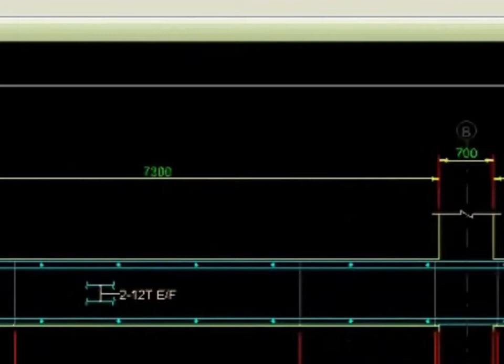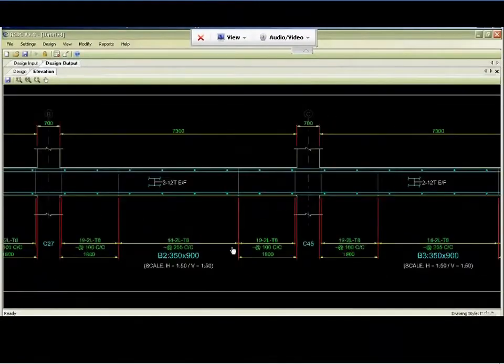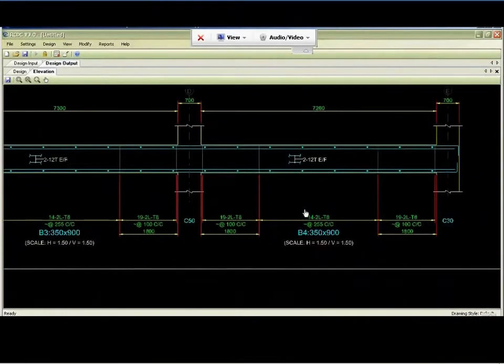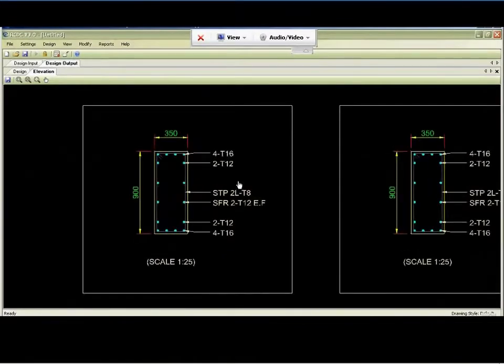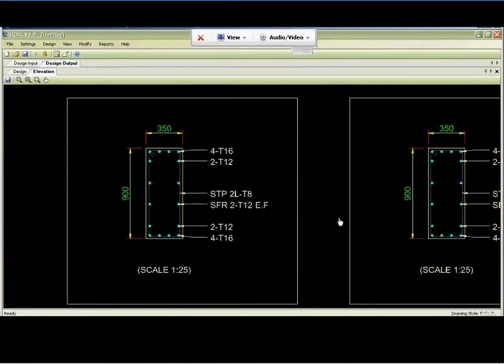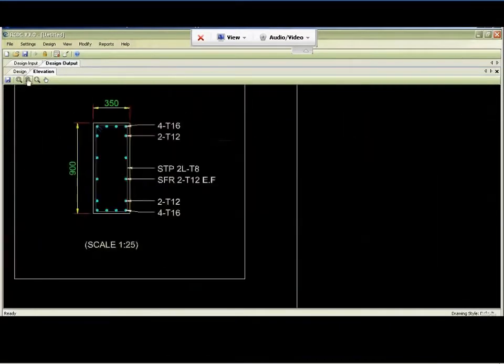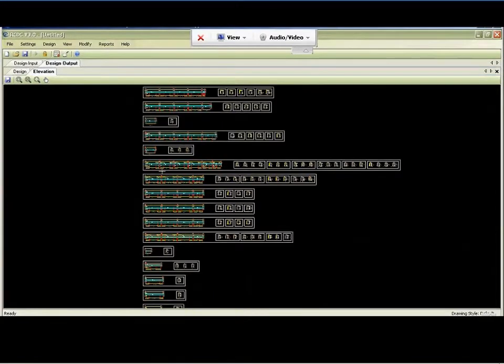We can just zoom into this with everything, spacer bars, the bends shown to scale, shear reinforcement, indicative grid lines, everything. And we can also zoom to show the cross section. So stirrups, face reinforcement, everything. In case you're using 4 or 6 legged stirrups, it will give you those.